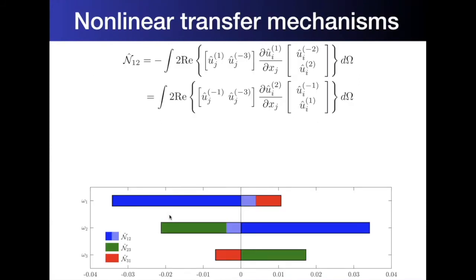So this figure neatly summarizes what's taking place in cylinder flow if you truncate after 3 harmonics. There are 2 transfers between omegas 1 and 2. One is energy being removed from omega 1 and given to omega 2. But there's also a small amount of energy that omega 2 recycles back to omega 1. So that's why we have 2 terms in this expression here. In this case, we can consider this the source mode, this the recipient mode, and these are the modes facilitating transfer.